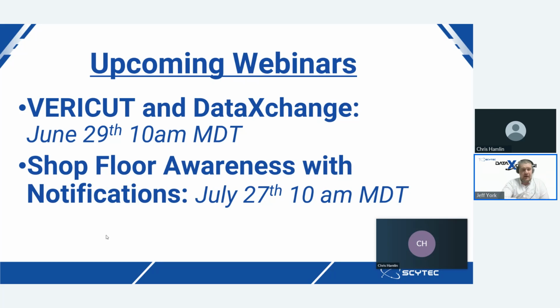And then at the end of July, there's a notification feature set that is very robust inside of Data Exchange as well. I'm going to be going over how you can utilize things like Microsoft Teams, text and email to get machine status updates sent directly to your phone or email. So let's say, for example, you have a machine that has been in unplanned downtime for longer than an hour, and you want to be notified of that. You can use these things we call expressions so that when it crosses over that half hour or hour in unplanned downtime, you will get a text message sent to your phone or an email describing what is going on.